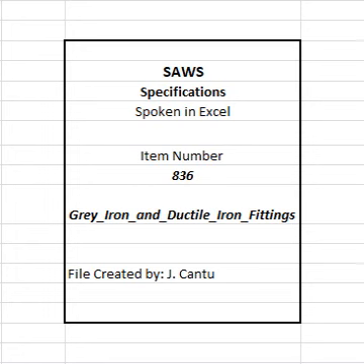836.6 Measurement. Ductile iron and gray iron fittings will be measured by their weight as listed in Table 836-1 of the specification of the various sizes of fittings installed. 836.7 Payment. Payment for gray iron and ductile iron fittings shall be for mechanical joint compact fittings, AWWA C153/A21.53 and/or flanged fittings. 1. Payment will be made at the unit price bid for each ton of fittings